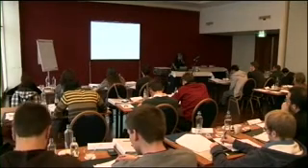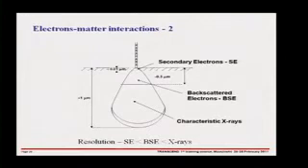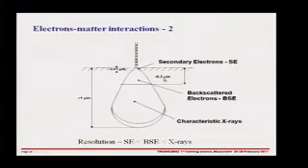Okay, so as I said, this is very schematic. We then have the backscattered electrons. Backscattered electrons are very easy to understand. It's just like bouncing a ball. The ball hits the floor, it bounces back. That's the electron. It goes in, it interacts with an atom, and it bounces back. And these, of course, have the same energy, more or less, as the incident beam, and therefore they can emerge from greater depths. Again, I think that's really an upper limit, 0.3 microns, I'd say. Again, it was much less.